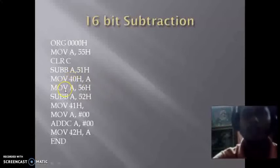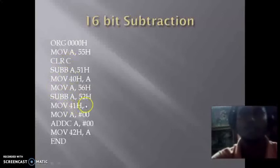Now we will subtract the upper byte, the content of 56 minus the content of 52. The content of 56 will be stored into the accumulator, and SUBB A, 52H. So we have to consider the borrow, and that's why we have to consider the carry. So in this instruction, basically the carry is used, and considering the carry, the data is subtracted, the content of 56 minus the content of 52, and the result will be stored into the accumulator.